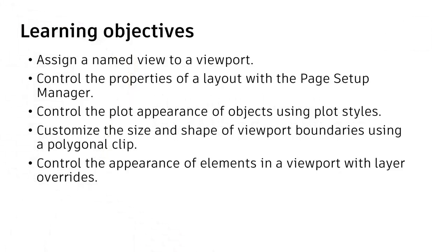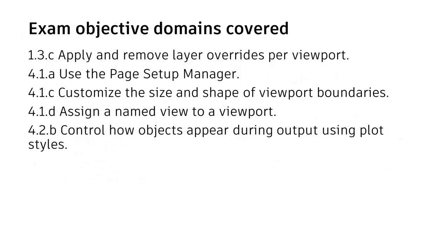I finished editing my drawing, and now it's time to set up my different layouts. I'm going to be using the Page Setup Manager to help me define how each layout will appear. Because my submittal package is going to different counties, I'm going to use plot styles to comply with each county's layer standards. Plot styles can be defined using a color table or a standards table.